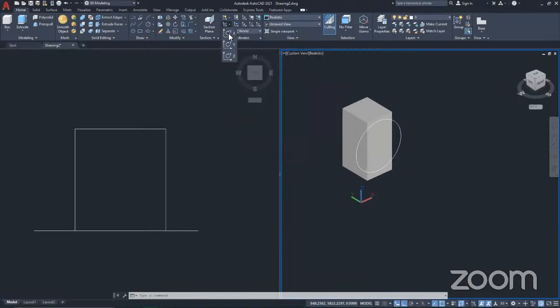So let's say I choose the X axis, for instance, and I come over here, you see, I can rotate my Y and Z axis about my X axis. Can you see this? Let me turn off orthogonal restriction so you see it clearly. And I think I'll have to remove dynamic input so you see what I'm doing. Like so. You can see it's rotating about the X axis. Can you see this? Please, if you can see this, use the chat box.